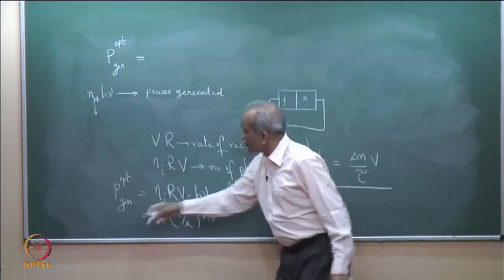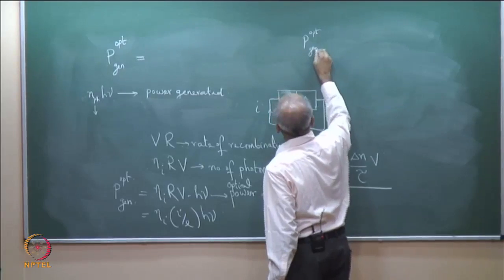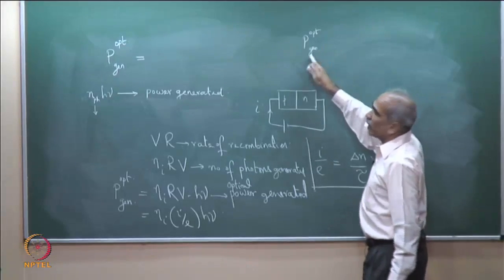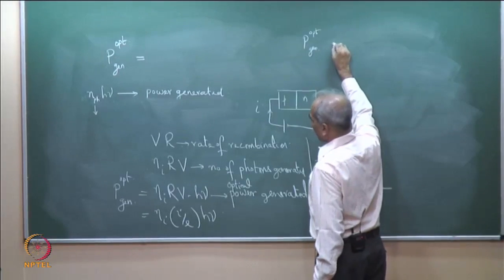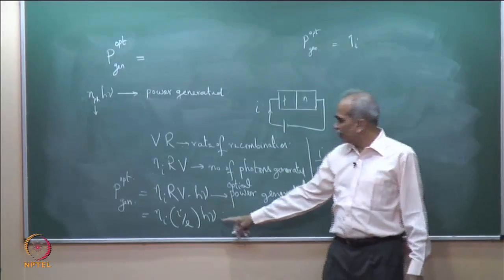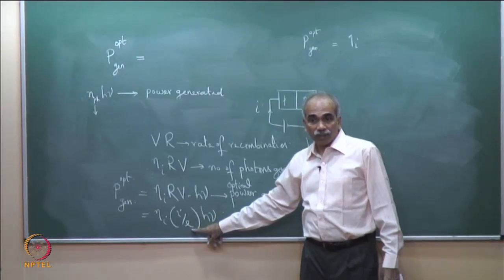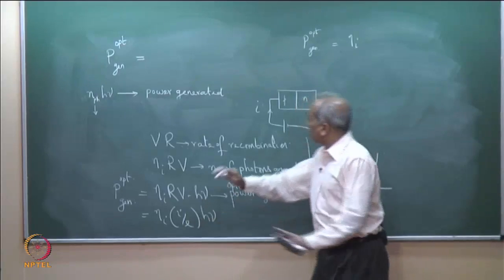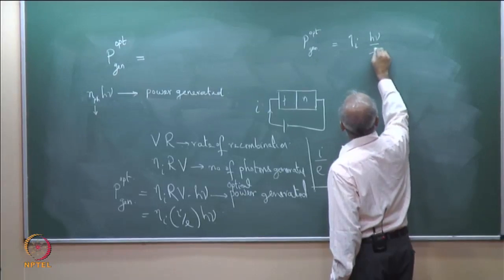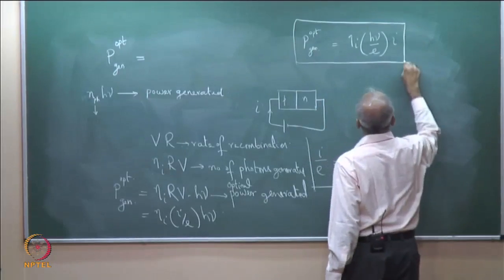I have got the expression for P optical; right now I am writing it, afterwards we will drop it, since we are dealing with optical power only. Just at this point I am writing P optical generated. Some things can be simplified here. H is constant, nu is C by lambda, and hc by E is 1.24. Anyhow, let me keep it as it is: eta I into h nu by E into I. So, this is the optical power generated.